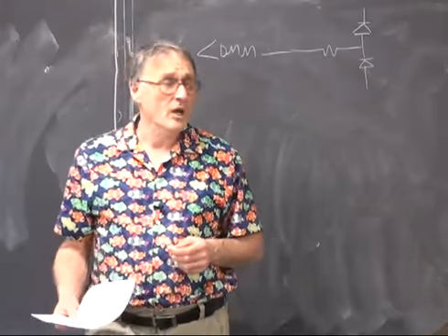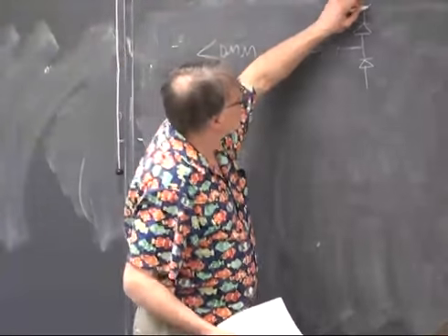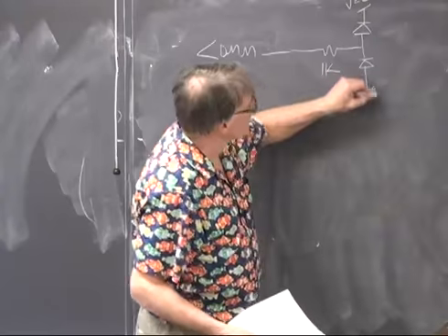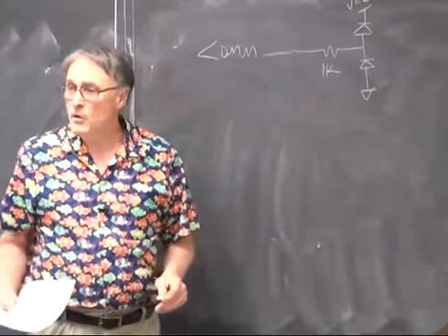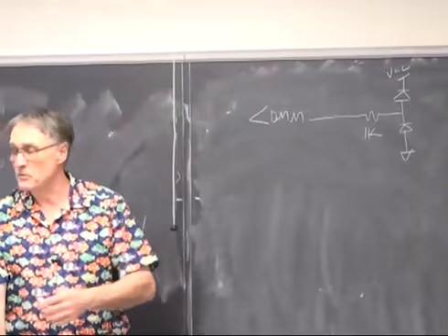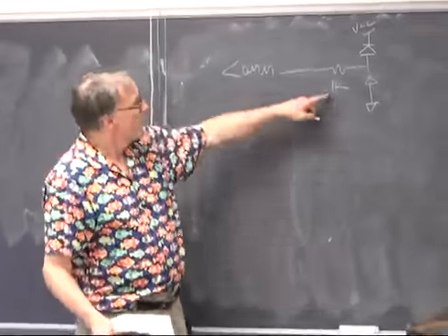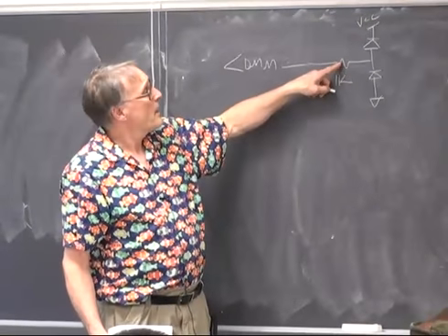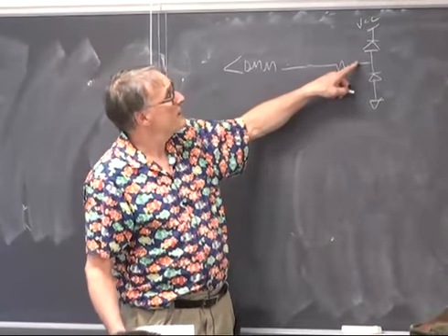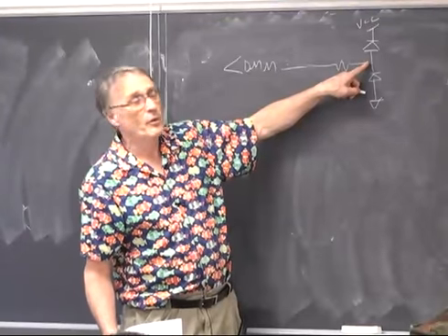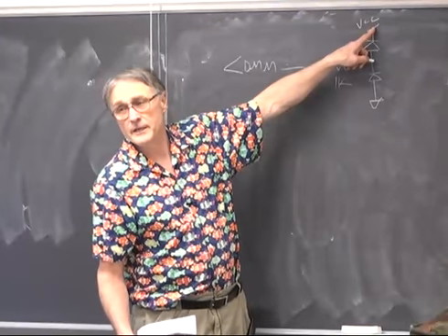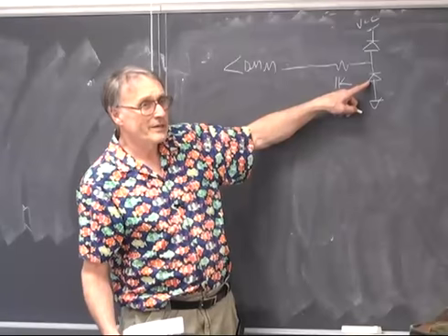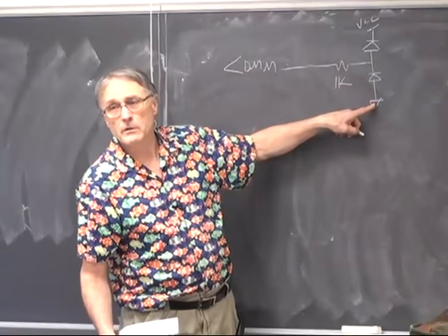So we're going to use a 1K resistor and a pair of diodes, called snubber diodes or clamp diodes or clippers. The 1K limits the current to something reasonable, and the diodes short any voltage above VCC plus 0.7 volts to VCC, and any voltage below minus 0.7 volts to ground.